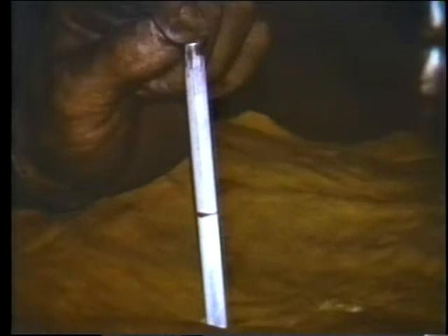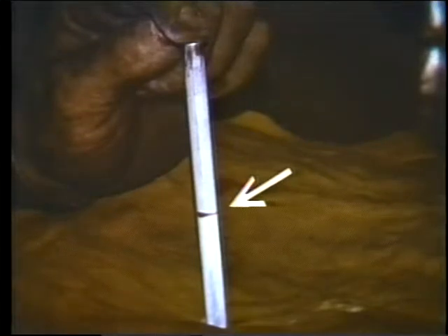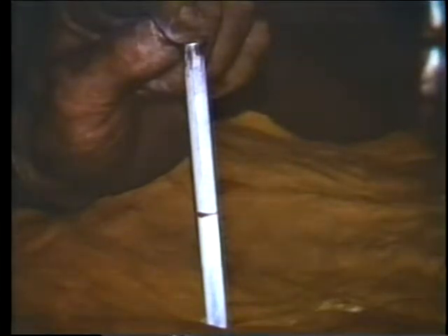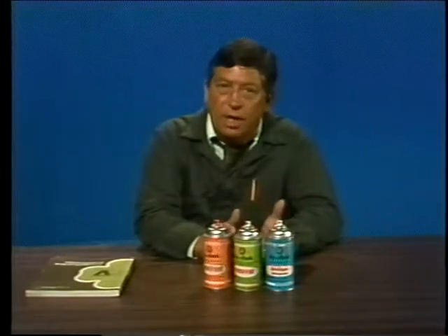Now, as you can see, the developer has drawn the dye out of the crack, and a clear indication of the flaw shows on the surface. This is what you're looking for when you do a liquid penetrant test. If you discover any indication, report your findings to a supervisor. Depending on the part, it may be tested again with some other method to determine whether the flaw is serious enough to demand repair or replacement of the part.